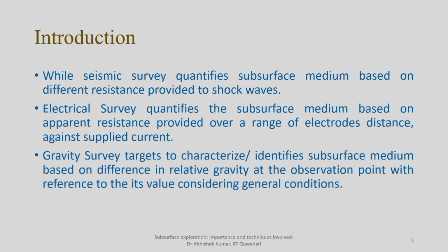In electrical resistivity survey, we again quantify the subsurface medium based on the resistance offered by the medium against externally applied current. Of course, this resistance will be measured over a range of electrode distances, so that we can understand the average or apparent resistance offered by different subsurface media with respect to depth.